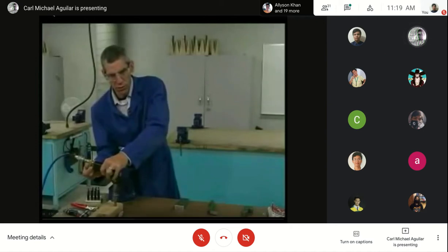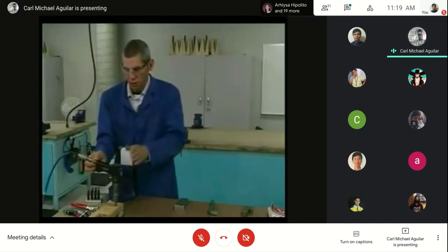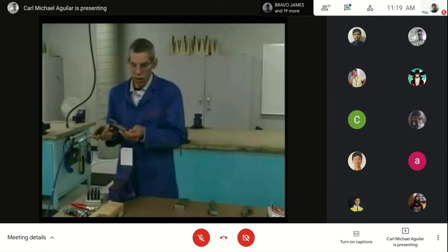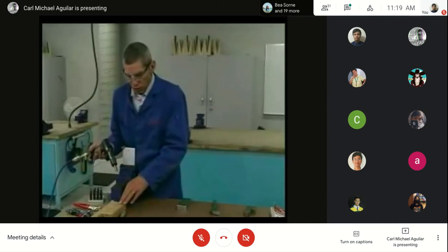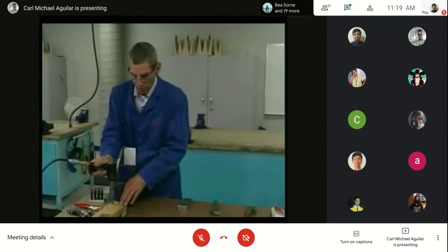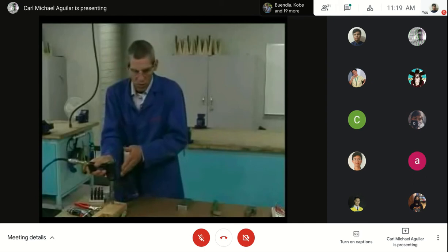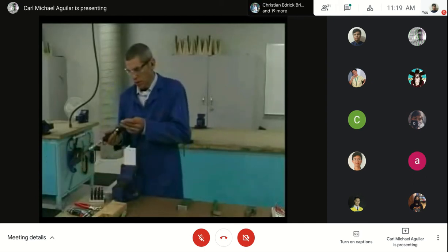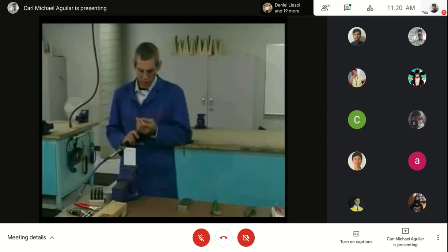A couple more notches. So it's just by hearing that you determine the hitting strength of the rivet gun as you're setting it. Looking down at the block of wood, I see that I am making a fairly good impression into the wood, meaning it's hitting hard enough, but the wood's not splitting, so I'm not hitting it too hard. So that's how you set the gun. It's strictly a trial and error thing by ear.